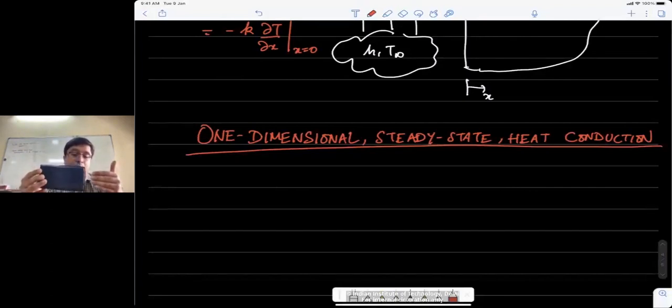In the transient phase, heat flows even in the other dimensions, because the transfer does not happen across only one layer. It has to happen across the entire layers, so there would be some diffusion of heat even in other directions. At steady state, we are so far away from this initial condition that all such perpendicular surfaces will be at the same temperature, but not before that.